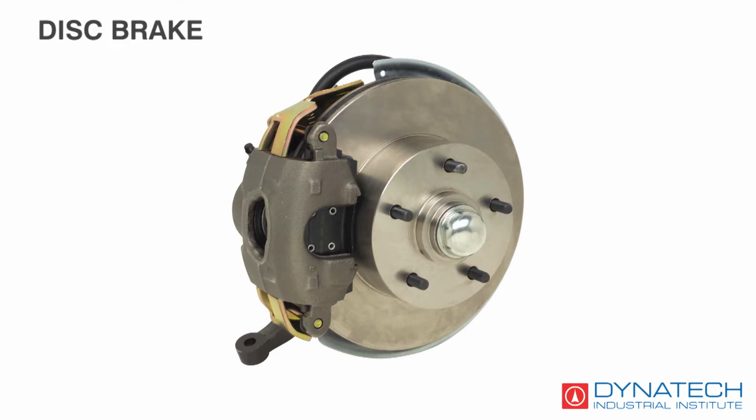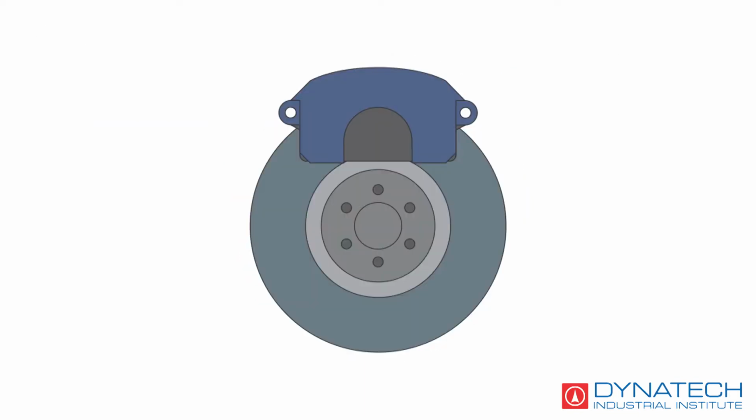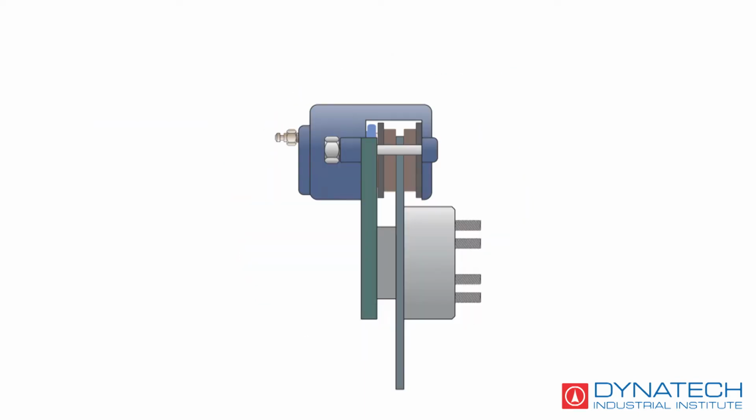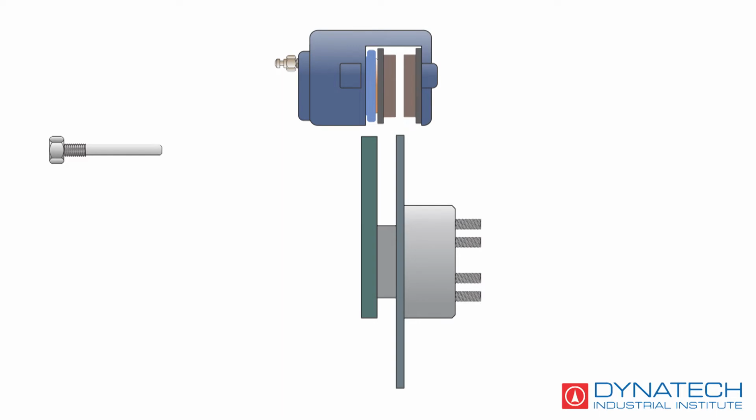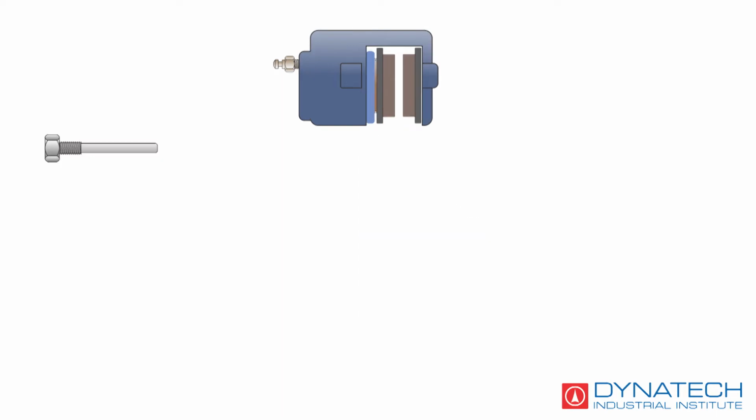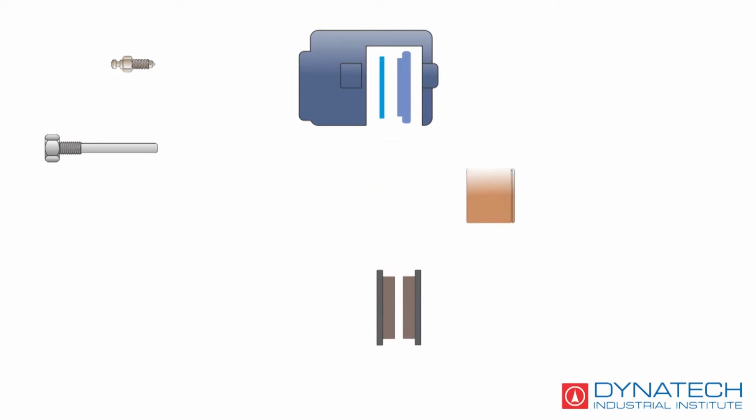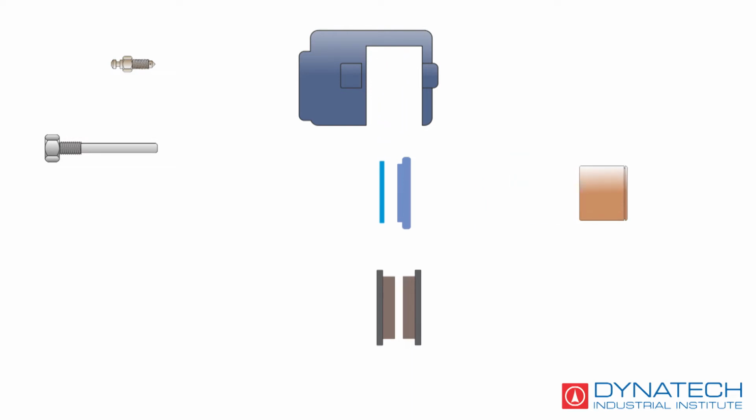Parts of a disc brake: disc caliper, rotor disc. To disassemble the disc brake: 1. Remove the anchor pin. 2. Remove the caliper. 3. Remove the disc pad and the bleeder screw. 4. Remove the piston. 5. Remove the dust seal and the seal ring.